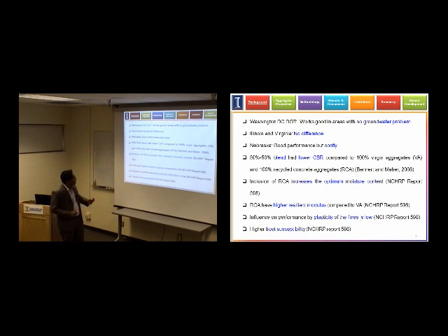So far, the DOTs have had a pleasant experience with these types of conventional blending, but from the literature review, we have also come to know that a 50-50 blend, that means a 1:1 blend of RCA and virgin aggregates, tends to have lower CBR, that means lower California bearing ratio, and inclusion of recycled concrete aggregates increases the optimum moisture content.